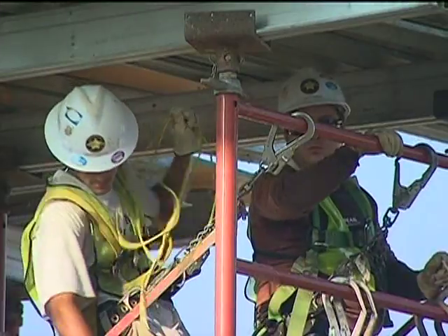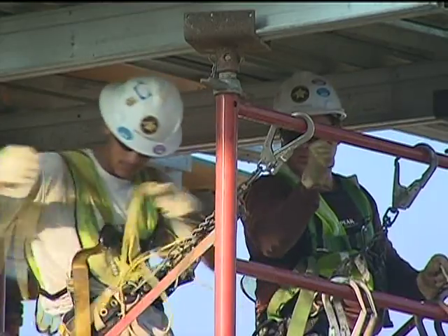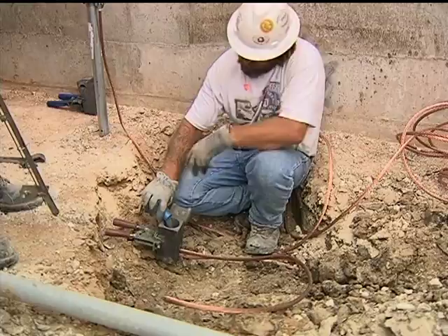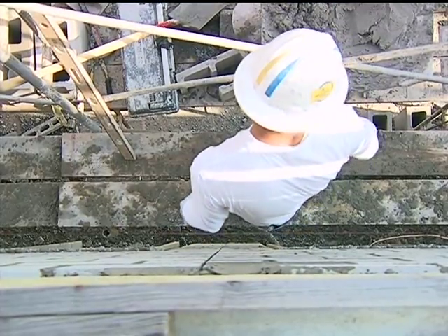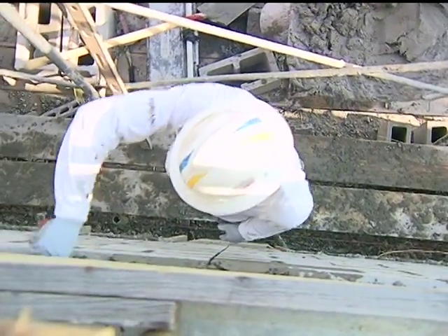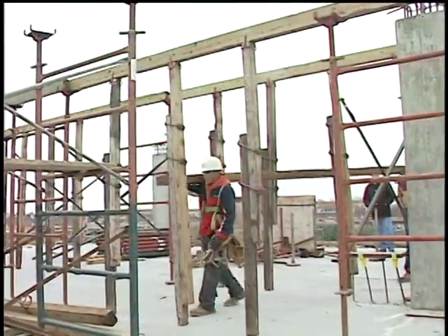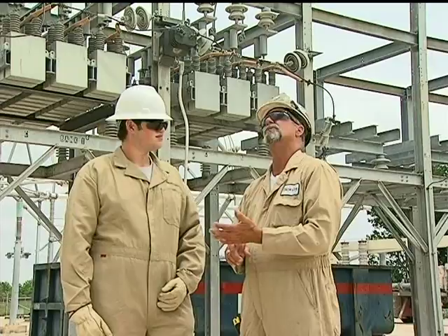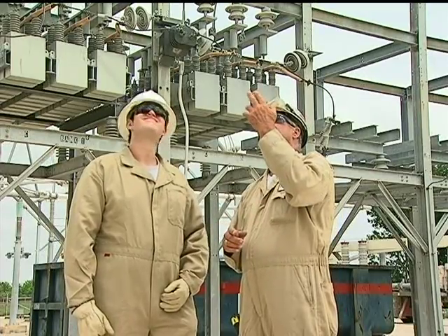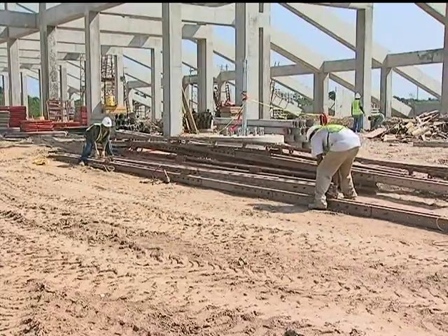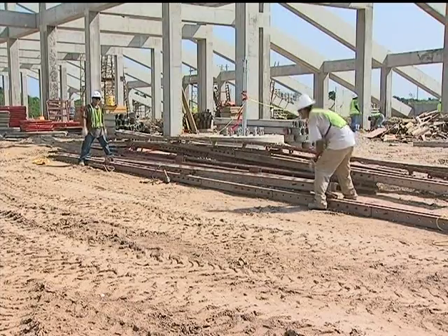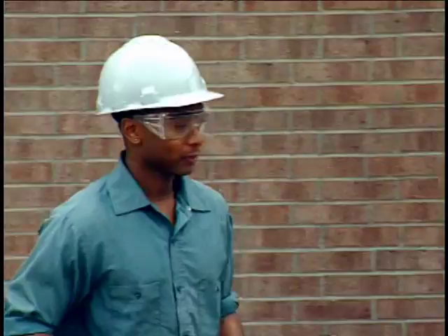Hard hats can protect workers from impact and penetration hazards, as well as electrical shock and burn hazards. Wear hard hats if you are exposed to risk of falling objects, bumping your head against fixed objects, such as exposed pipes or beams, or if there is a possibility of accidental head contact with electrical hazards. Be aware of special project or contract requirements that may require wearing hard hats at all times. Wear a hard hat that is appropriate for the hazard.